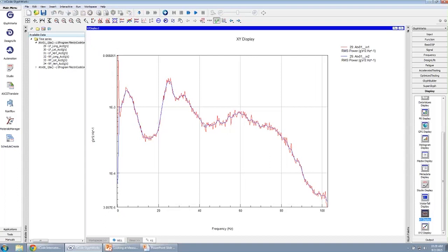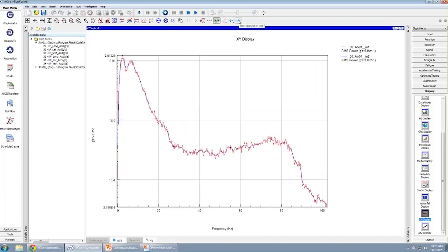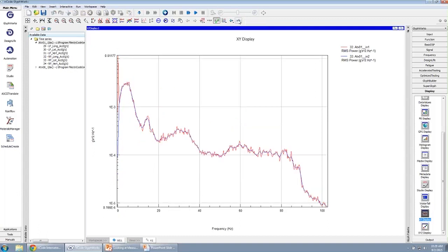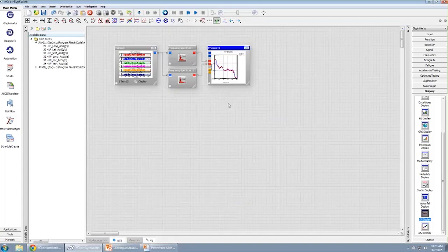So that's 1,024 data points versus 256 data points in each one of the buffers, showing us how the spectral resolution becomes less peaky when we include fewer data points in a particular buffer size. And this is going to be true for all channels. So I can use these blue index arrows and navigate through and look at all of the other 6 channels compared and see how that buffer changes.